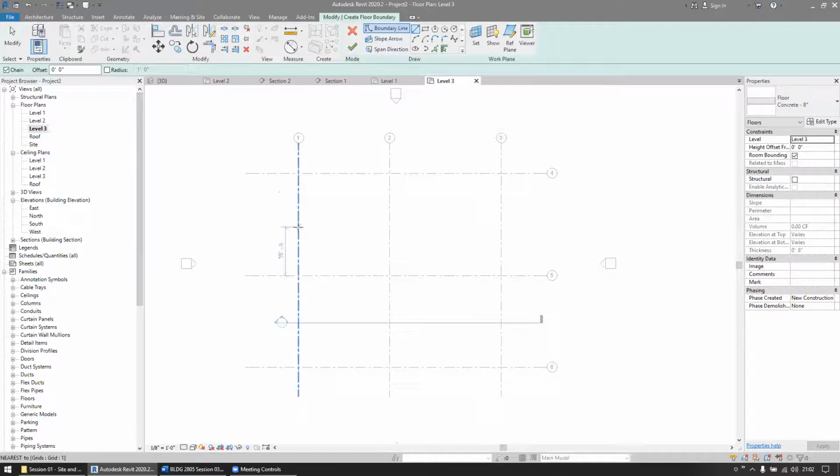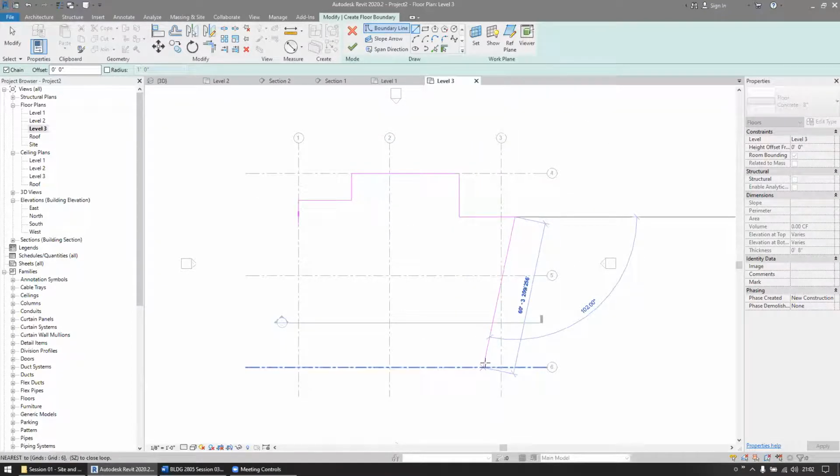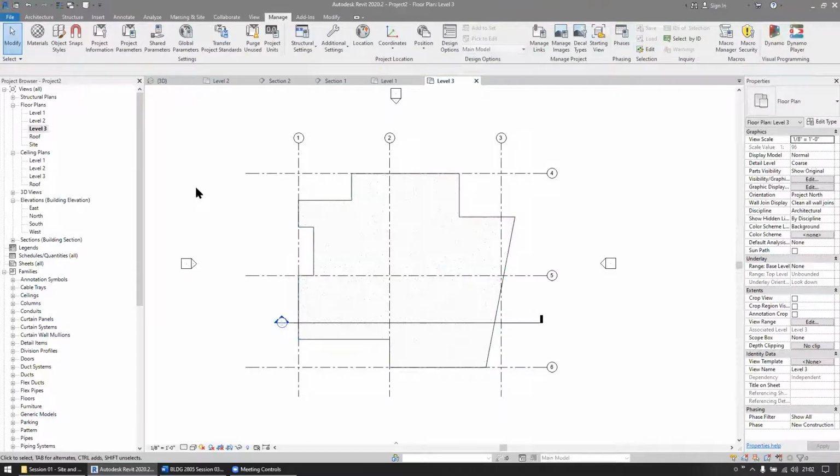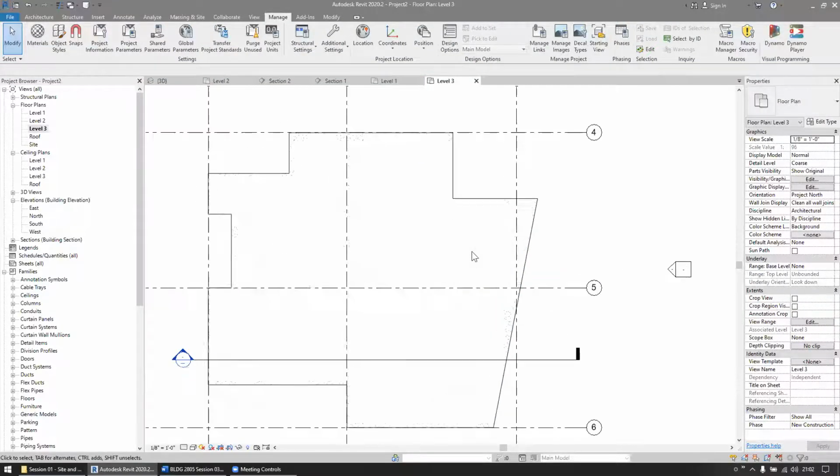Okay, so often when a slab plan is being done for a project, it's because the shape of the building is complicated enough that a slab plan is going to be really helpful, because the contractor really wants to know where the edges of the building are located. So in this case here, we've got our outline for the slab for the building, but we've also got some locations where there's going to be some balconies.